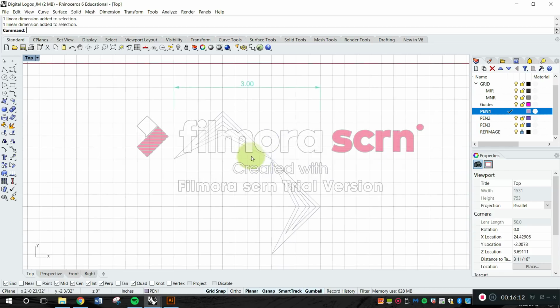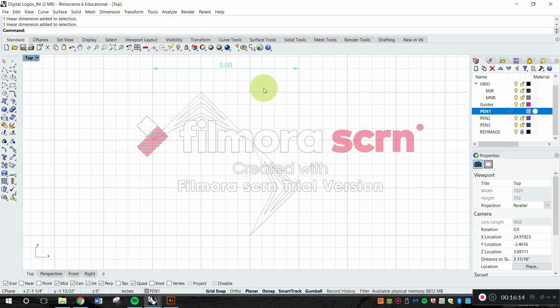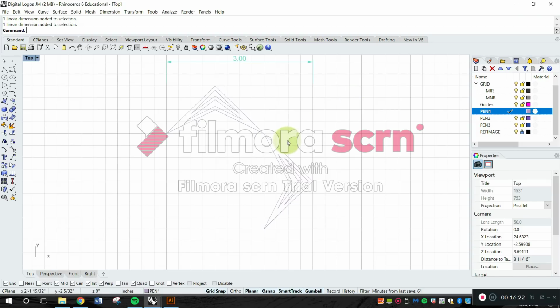What helps to continue adding dimensions is to actually start defining our grid. And like I said, we're actually going to use the default grid on Rhino to trace our own grid. How do we do that? Well, I'm going to select the major grid on. Remember, how do we do that? If we click almost right next to the light bulb, to the left of the light bulb, you bring a check mark onto the layer, and that's how you know it's active. That's how you specify that it be active.